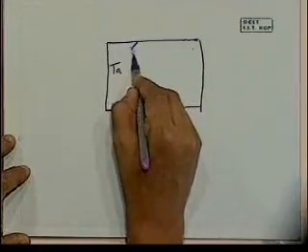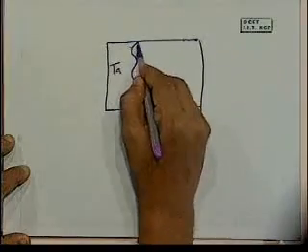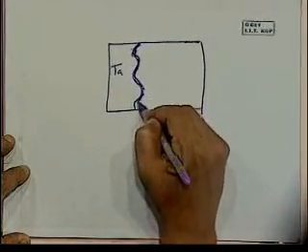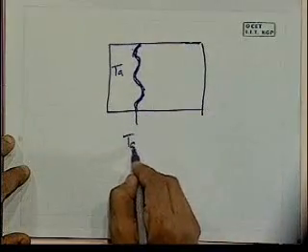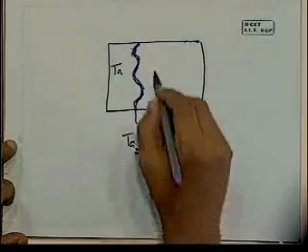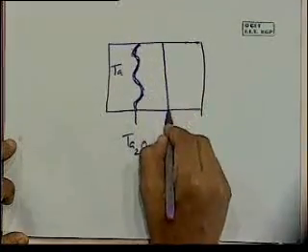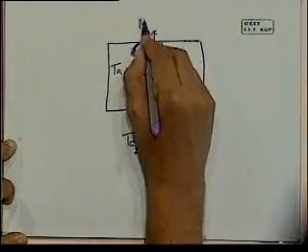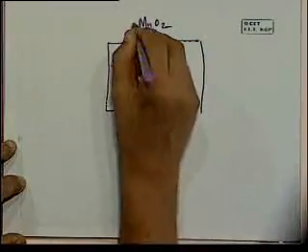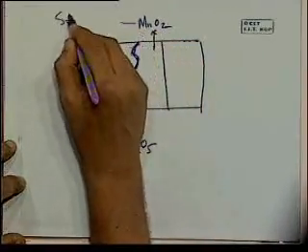And you also have a similar tantalum oxide layer that has been created, much like we did for aluminum. Ta2O5, tantalum pentoxide. Then we have a solid electrolyte, which in this case is MnO2, manganese dioxide, which is the solid electrolyte.